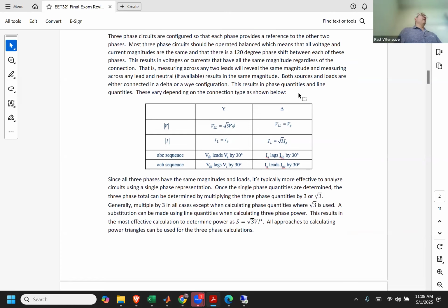And in a Y connection, you have 3 wires coming out, same as in a delta connection. The difference in a Y connection is you also have a neutral that you oftentimes don't run out unless you have a bunch of loads that are single phase off of whatever that Y system is. You oftentimes don't need the neutral because you're not going to run it. Again, we want a balanced system, so running a Y connected load makes the system unbalanced. So unless you're dealing with some lighting load where it doesn't make sense to run a 3-phase wire to a light because it's not practical, then we wouldn't run the neutral. So motors, transformers, all that stuff, you don't run neutrals out because those loads don't need it. It's a zero reference point.